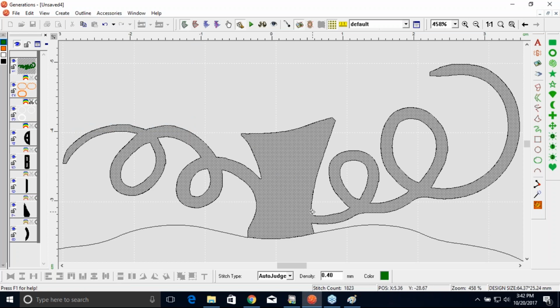So we want to start outside here. Left click makes a point, and left click. It acts like a scissors. And I'm not being perfect because I'm going to show you a little bit how we can clean it up. I'm going to come over here, left click and left click, press enter, and then it splits it. I do want to make sure that I'm outside both of the gray areas so that it can make a complete cut. Press escape to get out of the tool.